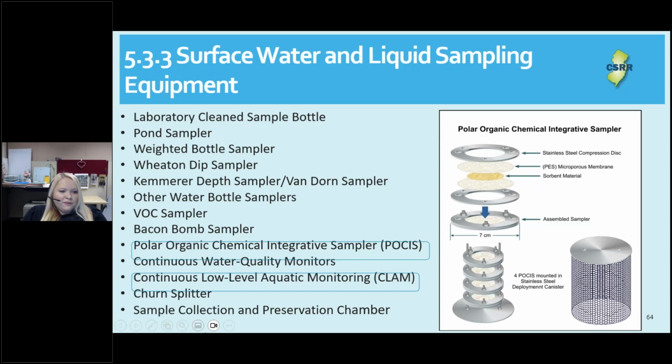It weighs about 2 pounds with a rechargeable battery and can actively sample water for up to 36 hours. The CLAM media is sheathed in a micro glass fiber matrix and kept in place with an encased shell. There's a pump with a calibrated flow rate. One issue that might be encountered is it can clog if there are high suspended solids. Next slide.